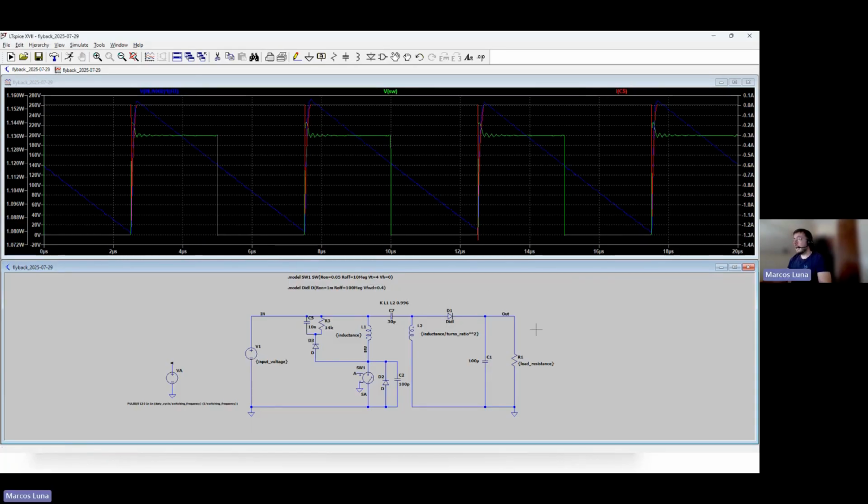And yeah, so the conclusion for this part is don't care only about the leakage inductance, also place the correct capacitance in the system, and don't forget about the parallel resistance, because as you can see, it has a huge impact in the hardware, okay?